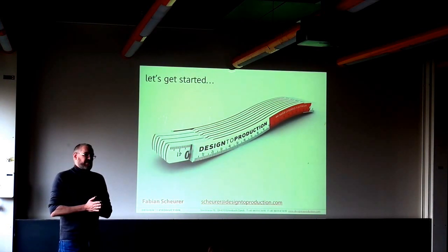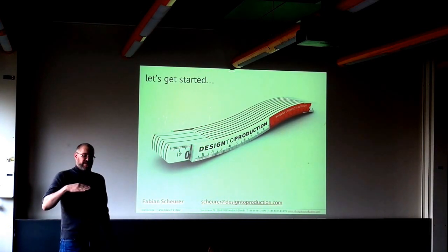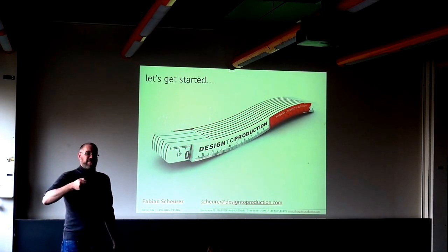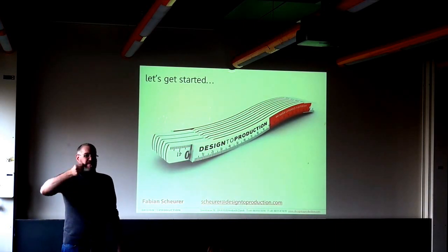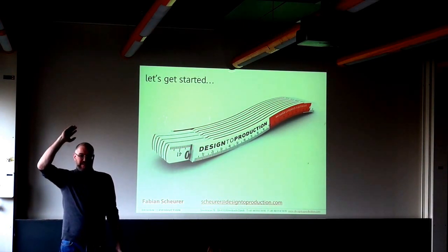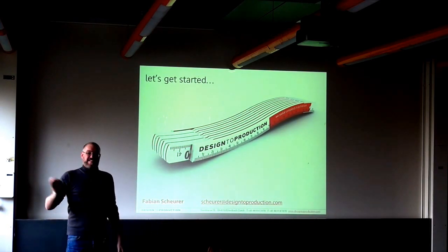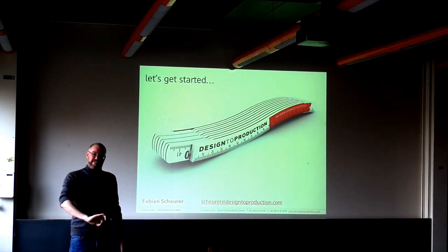Just one example: if you have a large facade where it's important that on every face of the facade surface the orientation is right, you put the normal vectors on every panel and make them 1 kilometer long. Then you get a hedgehog with very long spikes, and you see instantly if one of them is pointing in the wrong direction.